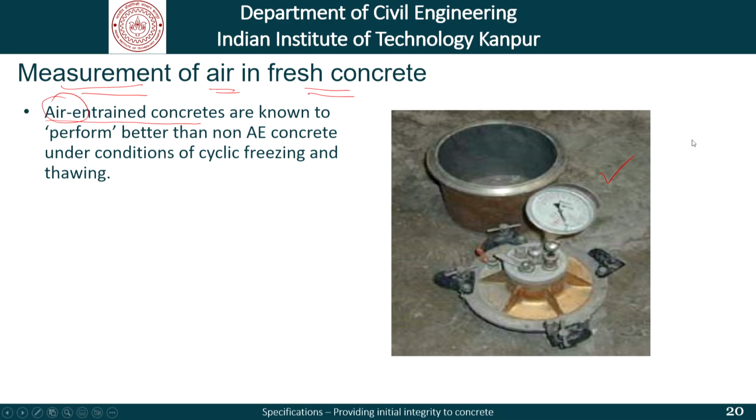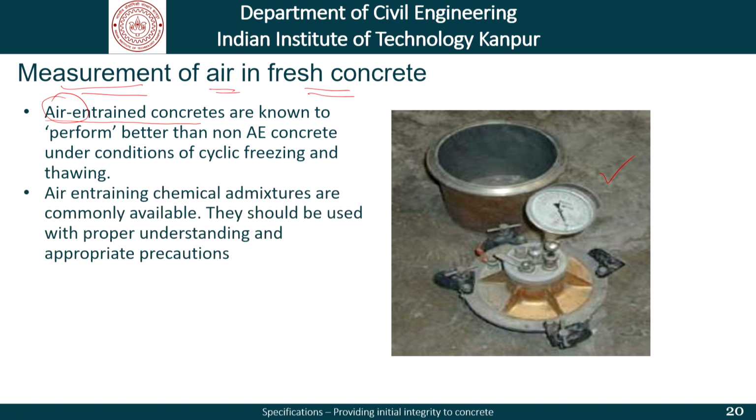Now that is something which in many engineering colleges we do not use, and I think it is only a matter of time that the use of these air meters would become more widespread. Air entrainment requires chemical admixtures which are air entraining chemical admixtures, and these are commonly available. There is nothing wrong in using air admixtures, but they should be used with appropriate precautions.